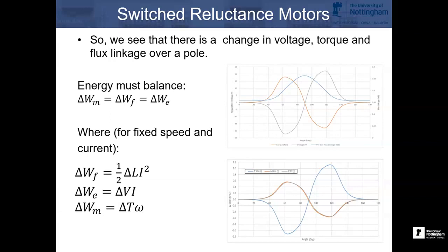And what we see is that in our simple two magnetic pole machine, we get a behaviour where we develop a torque as our pole starts to align, moving into that 90-degree point where we have full alignment, we have the highest possible flux linkage, and then as we keep moving that tooth away, we get the opposite effect.